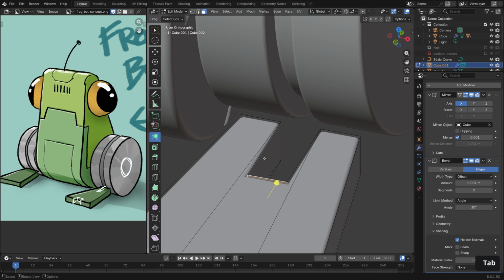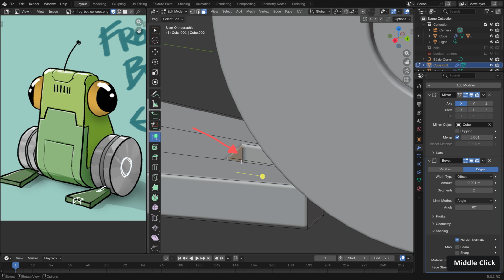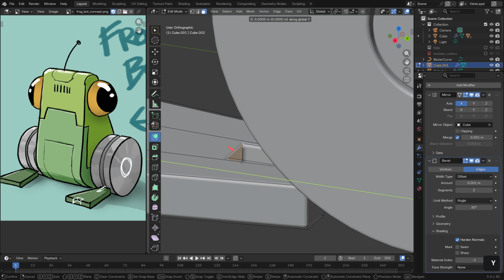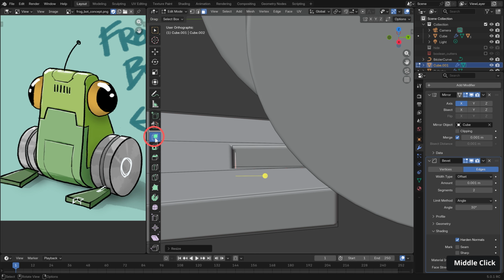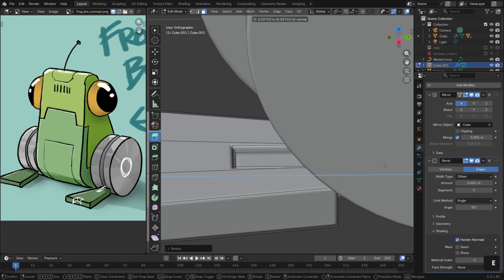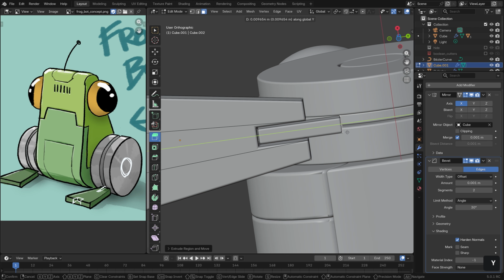geometry. So jumping in 3 on the number row or up here for poly select, we can use our poly here as an initial piece of geometry, so Shift and D, move it back along the Y, I'm going to scale it down a bit, and then we don't want our manifold extrude here. We could just use our regular one or hitting E on the keyboard to extrude the geometry back. And then G and Y, maybe to go a little bit further.